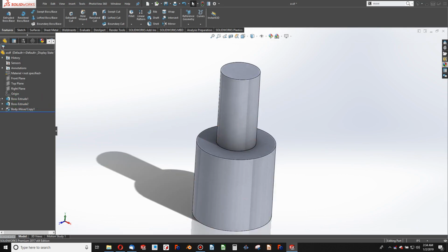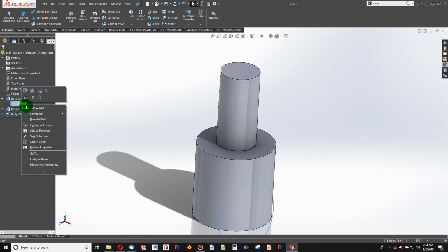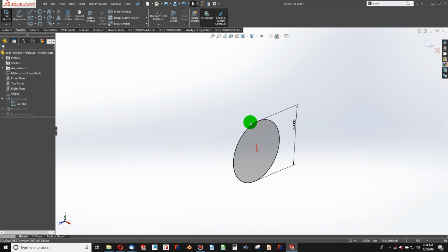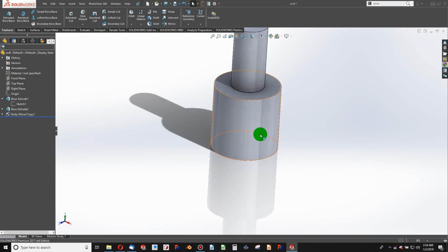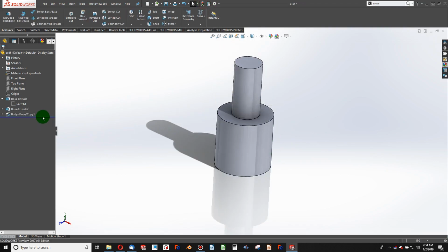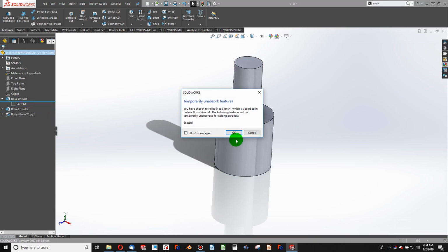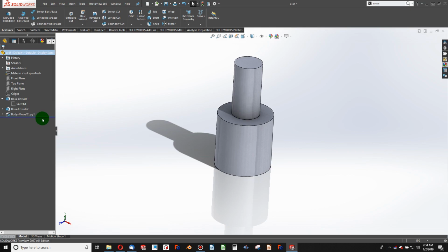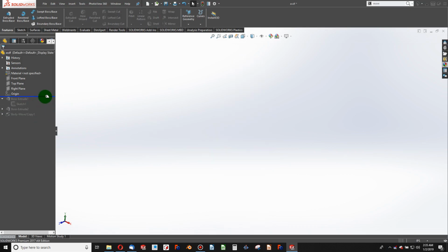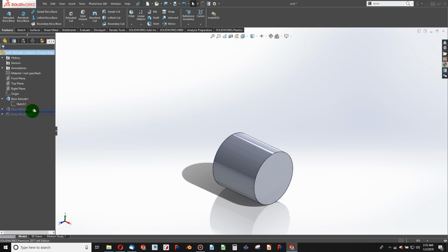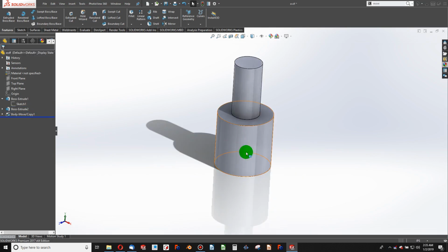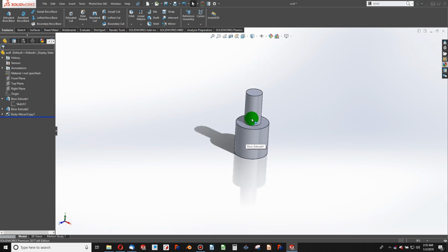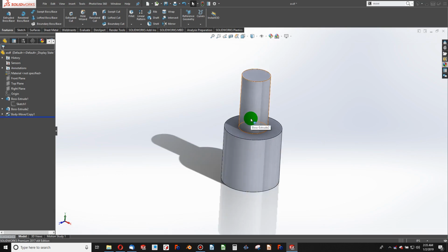Of course, it can be a little bit confusing because I can go to this, edit this sketch, and they don't really line up because I've moved the body. And so when SolidWorks goes to rebuild, it builds it the way that it was originally modeled, and then it goes in and reorients it afterwards. So be aware of that, but move and copy bodies is another more robust way than saving an assembly as a part for reorientation. Hope these things were helpful.